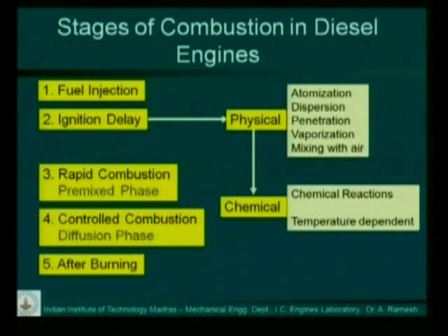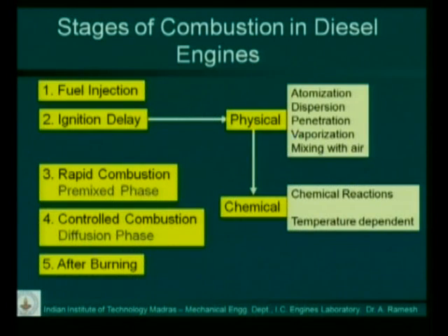And the next portion is the chemical portion, which is supposed to follow the physical portion. And here the chemical reactions start and they become self-sustainable, and the combustion reaction becomes active. And this is highly temperature dependent. In fact, both are temperature dependent, but the chemical phase is highly temperature dependent. And these two delay periods may be something like 1 millisecond or less than 1 millisecond in a diesel engine.